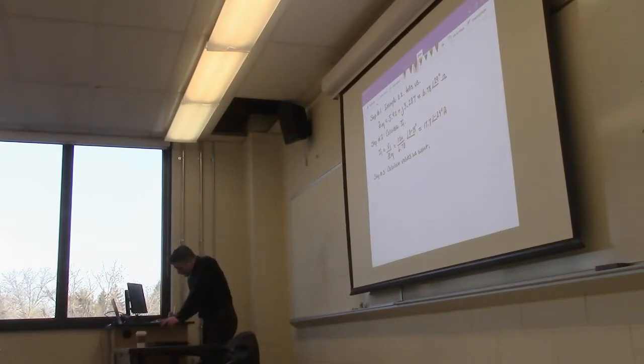Okay, so P is equal to the magnitude of V, magnitude of I, times the cosine of the power factor angle, which in this case is going to be what? What's the power factor angle? Positive 29 degrees, right?